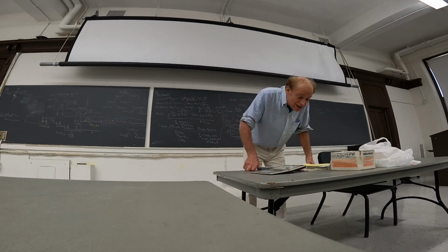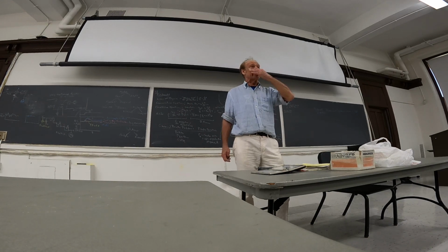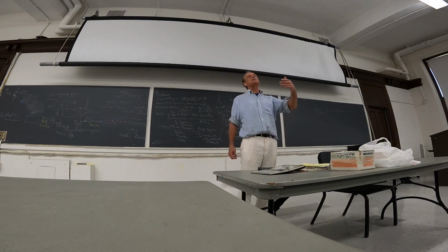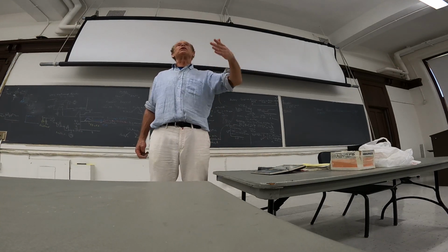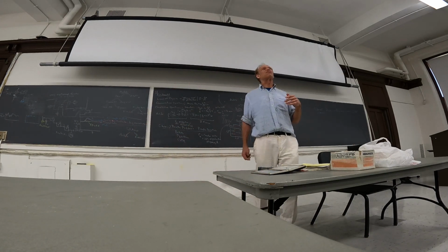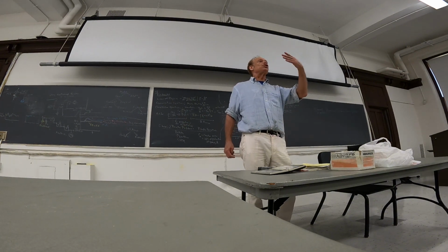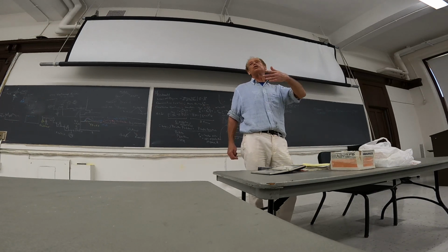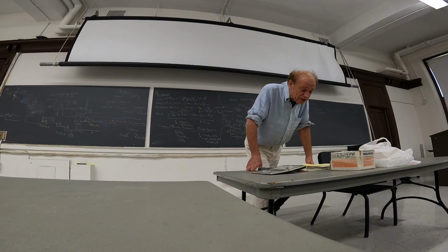The total there is equal to the flow part, the energy that's going in and going out, plus Q minus W, the heat being supplied, minus, depending on what thermo you use, either minus the work done by the system or plus the work done on the system, whichever way you prefer defining W. And of course, if I have a constant volume system, then typically, instead of using U for the internal energy, I would use the enthalpy H, and as a result, the work would just be the shaft work. So that's all thermodynamics, which we don't need for this particular problem, but that's something that we do in general.